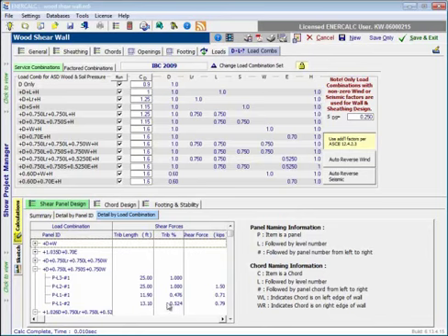the named panel. And then we use that percentage and the total shear at the level to report a shear force for that level. So the detail by load combination sub-tab really is just providing us with shear forces and tributary percentages for each of the panels. Here on the right hand side is the nomenclature that we're using to define panels, levels, chords, and so on and so forth.